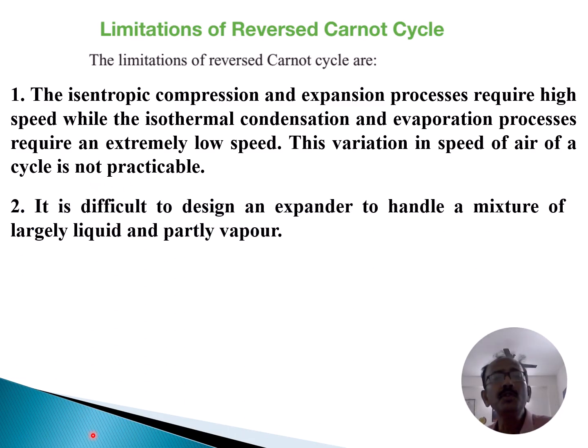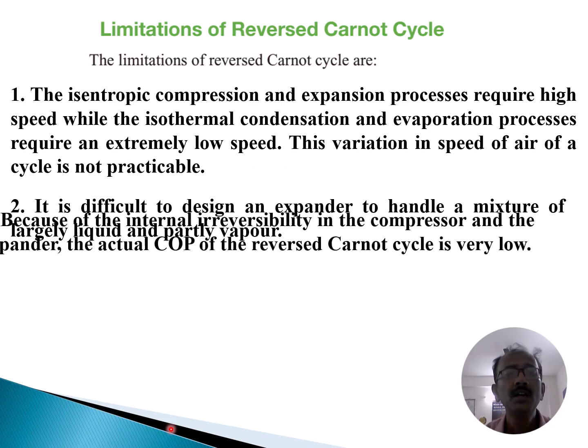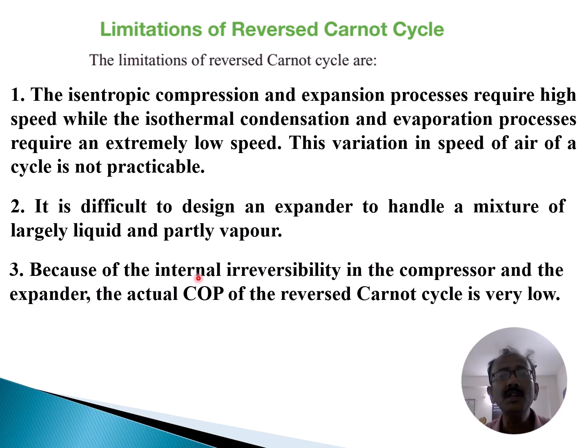Number two, it is difficult to design an expander to handle a mixture of largely liquid and partially vapor. That type of expander is quite tough to design. Number three, because of internal irreversibility in the compressor and the expander, the actual COP of the reverse Carnot cycle is very low.